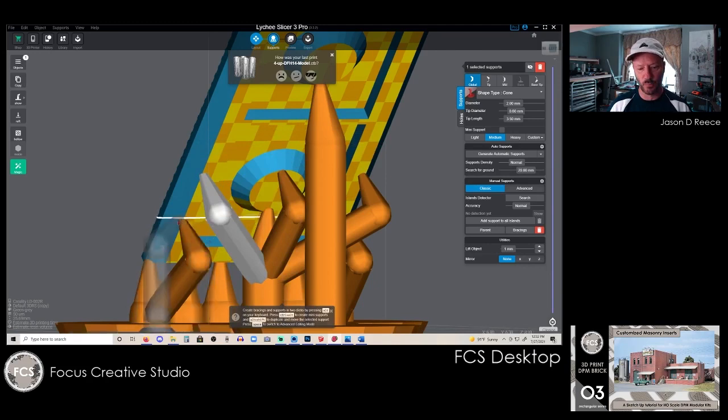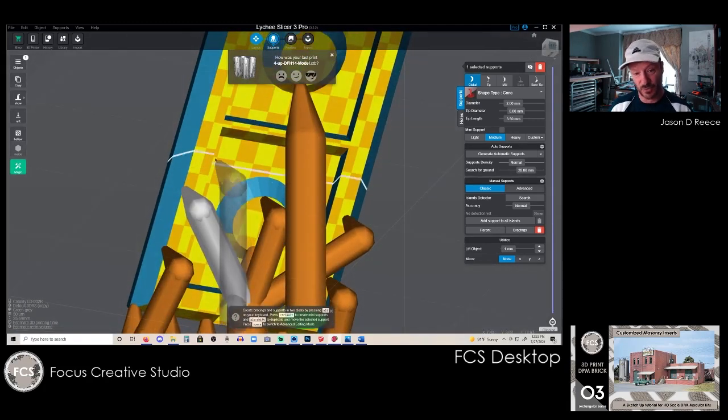So if you just line your supports up randomly, you're expecting that support in way too many instances to try and carry the weight and support of too much material. If you line them up like this, now I'm saying I've got 3 supports that anchor this model at this particular height of the model. So the force pull on the model stays consistent as it goes up, and it's not being changed by supports in different locations. It's just something that I've learned increases the success rate of my supports.